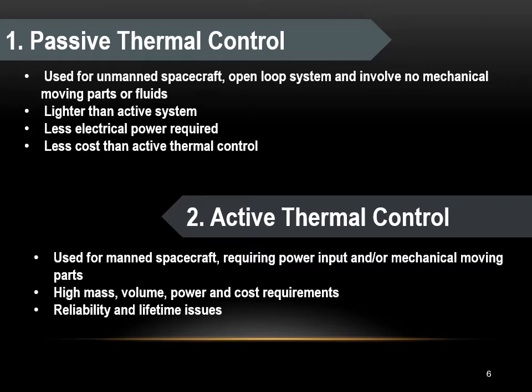Next, the thermal control elements. There are two types of thermal control method, passive and active. Passive thermal control is an open-loop means of controlling the spacecraft temperature by carefully designing the entire system to regulate heat input and output and creating convenient heat conduction paths. Meanwhile, active thermal control employs working fluid, heater, pump, and other devices to move and eject heat.